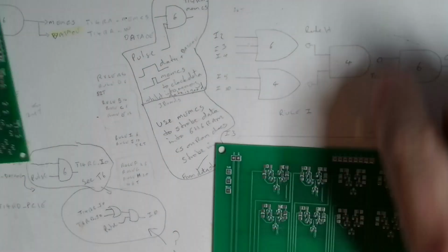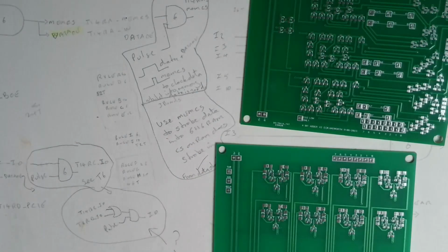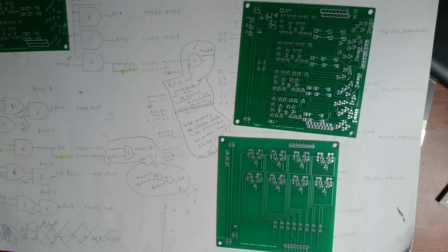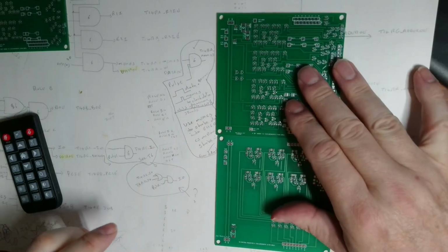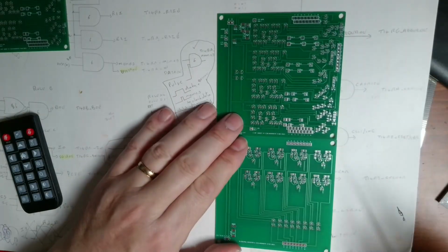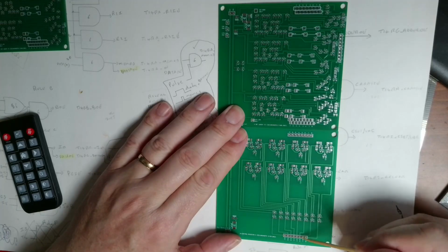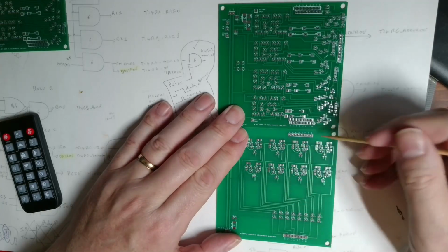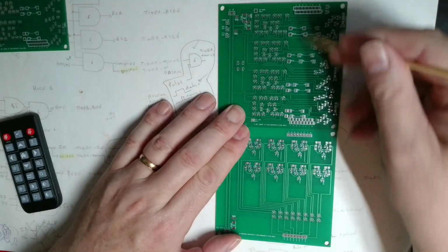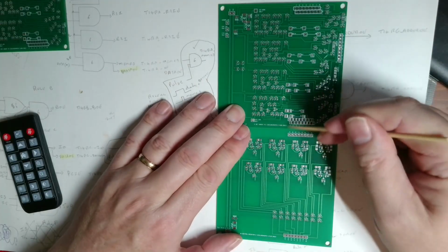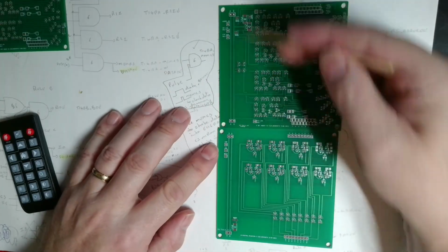So this board, we zoom out again. So you do it like this. The B register would actually be connected down here at the bottom, and will feed up through whichever circuit you want into the B port of the adder, linking across here, and your supply just linking down there, down all the boards.